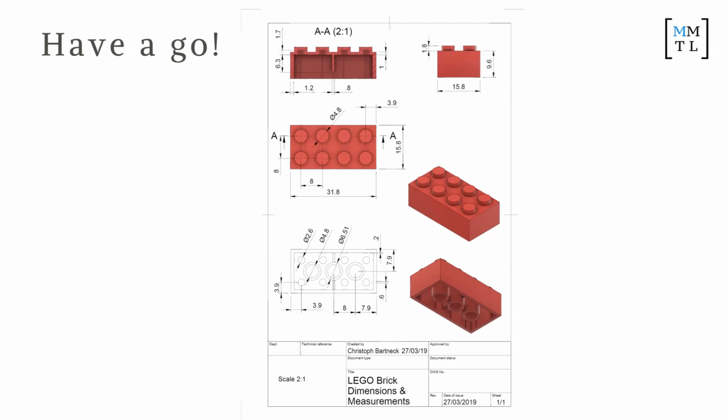Another way, keep in mind, we were saying before, is that you should do one column first, so cut out one column first, and then extend the pattern to the other ones. But it doesn't even matter, 1.7. And you don't have to duplicate it. No, you just use pattern. So just do it for one, and then figure out how to hollow out the columns. Then you can repeat it.